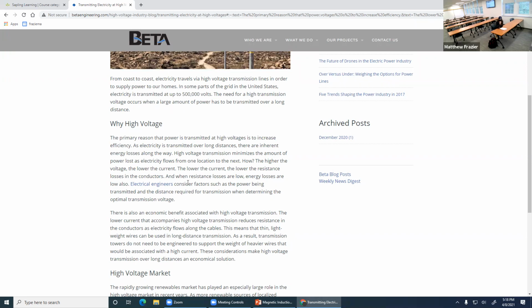So in the power line, there is, say, your blender. That is the main user of power. And then there are all these other losses. Because voltage is going to go down? Let's say you're going to lose a volt over a mile and you're running a power line for a mile and you only have 2 volts on it, you're going to lose half your power. But if you have 10,000 volts on it, that makes sense.